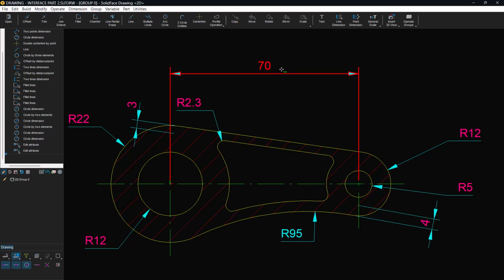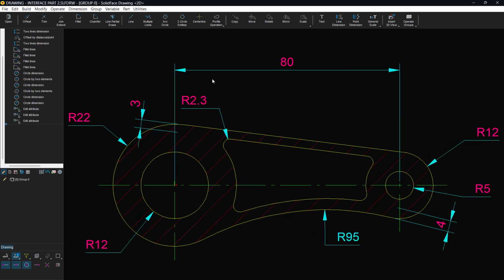To complete the detailing, define a recess or groove on the upper tangent line. This type of construction is normally done before filling. But let's do it at this point and then correct the filling. Creating a perpendicular line at the midpoint of the tangent line. Activating the simple straight line function by midpoint and positioning at the midpoint of the tangent line.